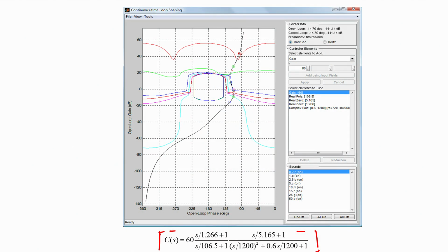And if you look carefully, we also notice that the Nichols plot of the loop gain, which is shown by the black curve here, is avoiding the forbidden circle, and this in turn implies that our closed loop system is going to be stable, and the maximum value of the transmission function is going to be actually much less than 3.5 dB. If this loop just touched this forbidden circle, then for some particular combination of the plant's gain and pole locations, we would have the maximum value of the transmission function to be exactly 3.5 dB.